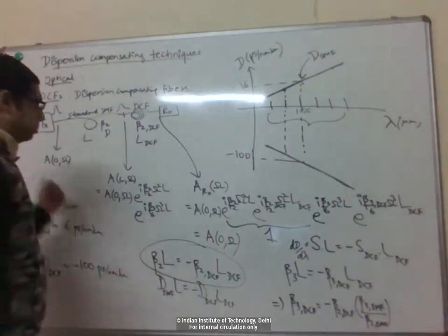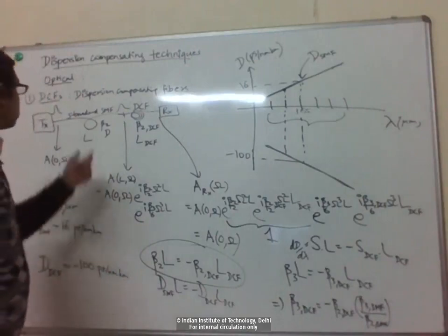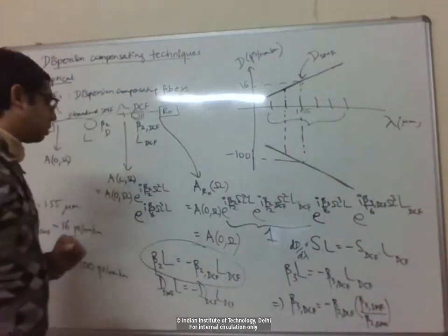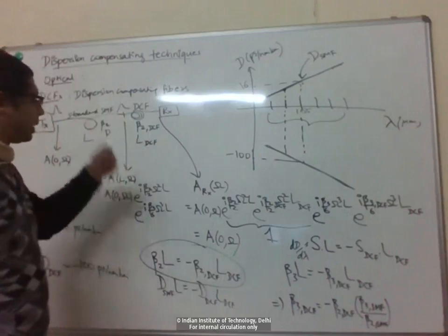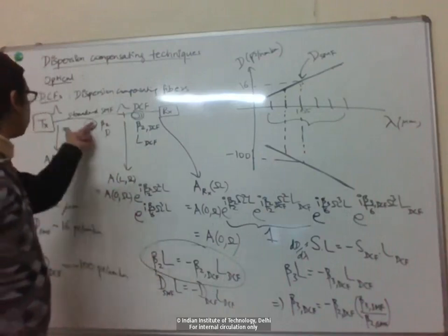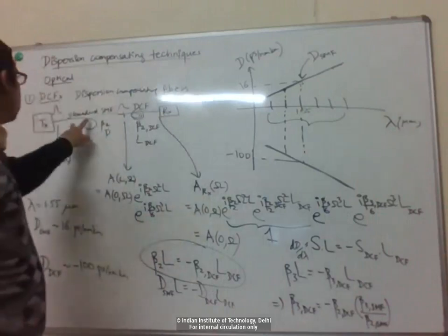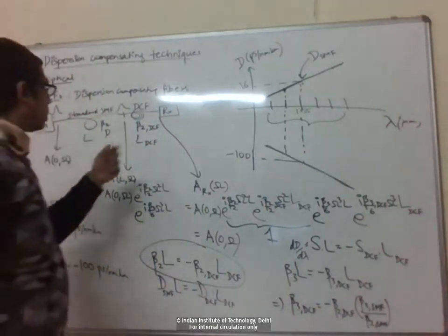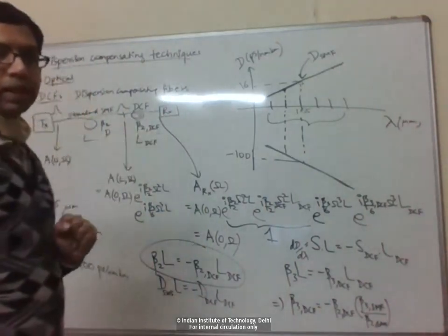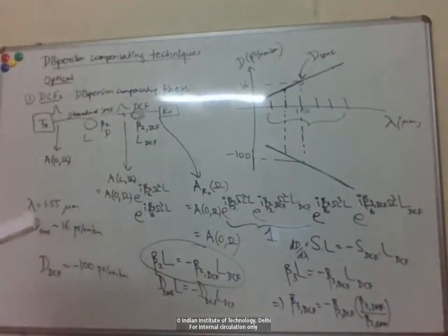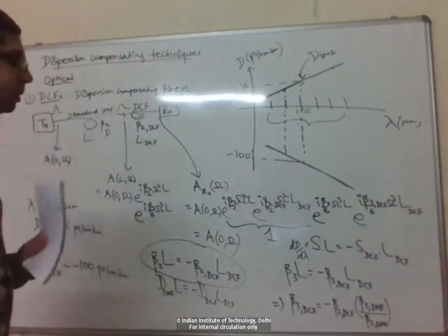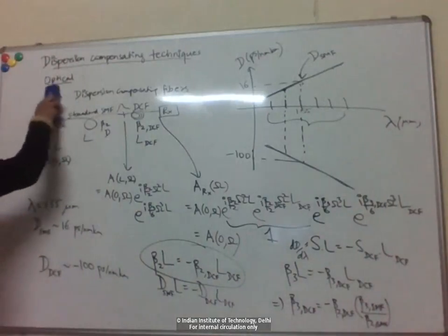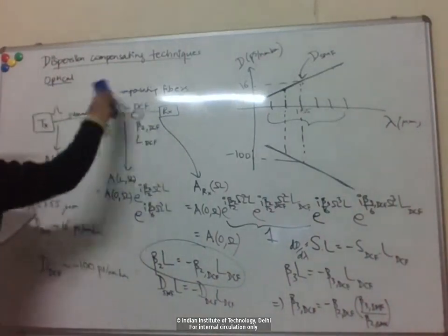Okay, so that's one optical way, but it's usually expensive. These dispersion compensating fibers are expensive, and you typically need many kilometers. We saw roughly you need like 1/6 the length, so if we have hundreds of kilometers of fiber, you still need like hundreds of kilometers of DCF, and plus you have to compensate for the additional loss, etc. So it's used in some places, but not everywhere. So let's look at another optical technique. Any questions on this?